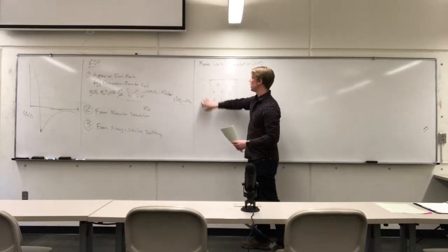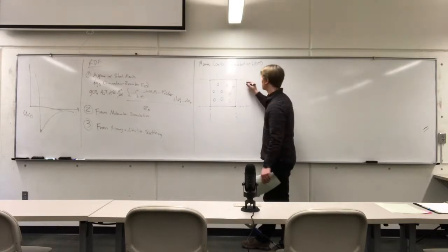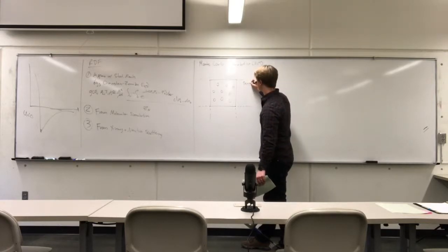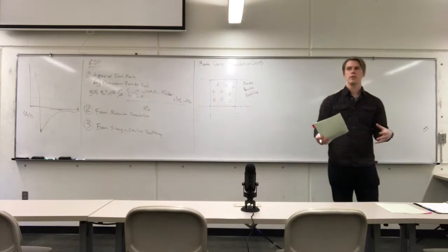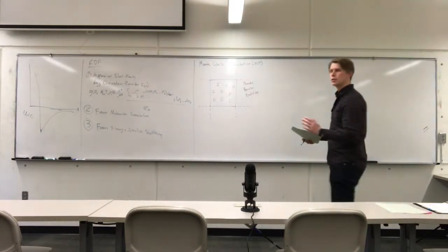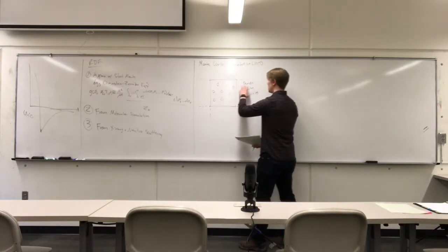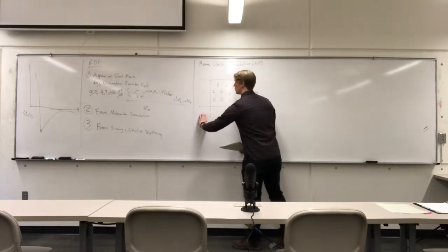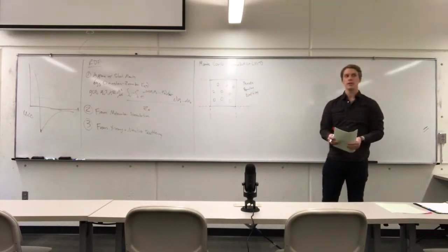I drew these dashed lines because in most all simulations we do something called periodic boundary conditions. The idea behind this is we're simulating an infinite fluid, so we don't want to have any interfaces or walls or phase changes. So the idea is we take this box, we put it here, we put it here, we put it here, we put it here, right? And we tile the system. So it makes it seem like it's more infinite.